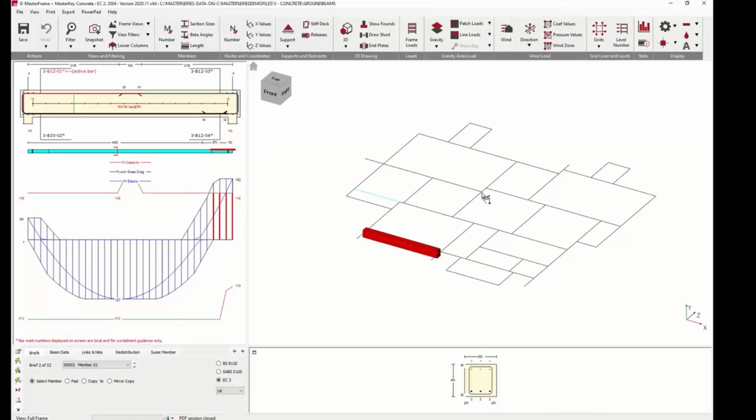You don't need to do a pile cap design on these because normally these are individual piles, and as long as the pile is not less than half the width of the section, then the gross cross-sectional plane shear will cover it, and you won't need to look at the punching around the perimeter.